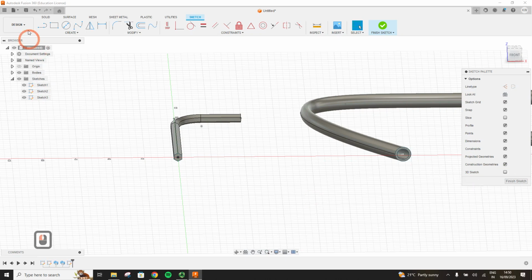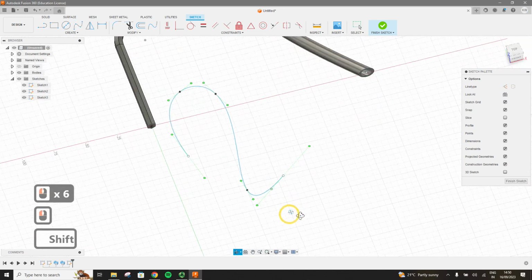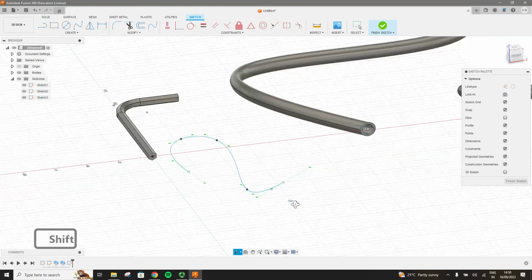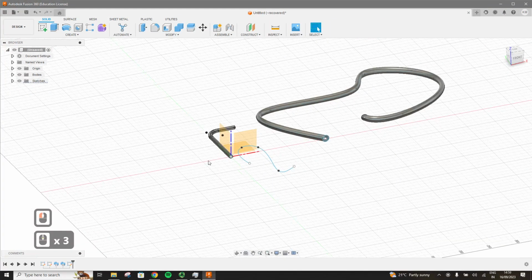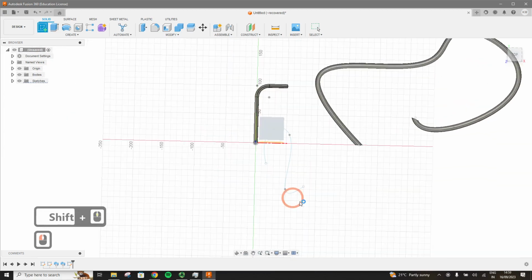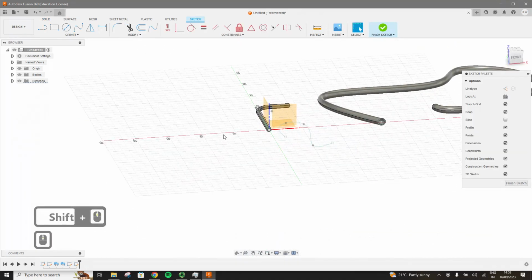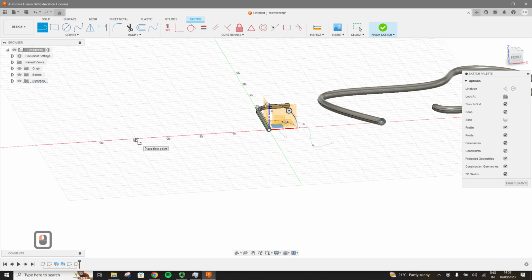If it is off, what we are constrained to is drawing in the plane. So even though it looks like it's in another plane and I revolve it, we can see that the spline never escapes the plane. For 3D sketches, I want you to be really careful because it can get really complicated very easily, because we can only see in 2D while making 3D sketches and we perceive something and it's actually drawing something else. So it's important to draw some constraints or some construction lines before making the actual sketch. So make sure you've enabled 3D sketch.